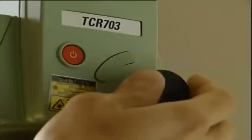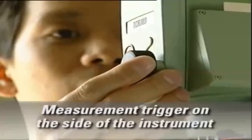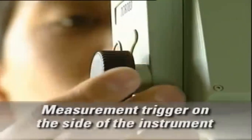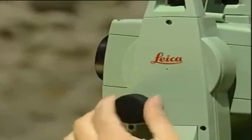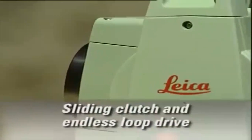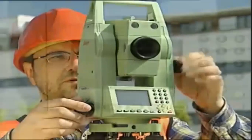With the TPS 700, you get many helpful extras included. For example, the measurement trigger located on the side of the instrument. It means that while measuring, you do not lose sight of the target. It is most helpful when a lot of points have to be measured. Or the sliding clutch and endless loop drive: no awkward clamping, tightening, and loosening. Instead, you just simply and comfortably turn the knob in the same direction.